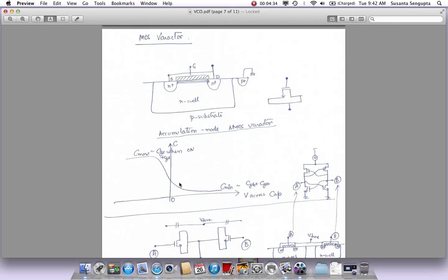So in this plot, to be consistent with this plot, what you have to say is the gate is fixed and the drain is moving. The gate voltage is kept fixed and the drain voltage is negative compared to the gate. Then this is heavily turned on and we're going to get Cmax. But if you kept the gate the same voltage, and you moved the drain to be more and more positive, so the source and drain value became more and more positive, then your VGD, gate to drain or gate to source, became negative. That means now you have depleted this channel of electrons and you have generated more and more holes, and your capacitance has gone down to CGDO and CGSO. So this capacitance movement will happen something like this. This is called the CV plot. What is the capacitance seen between these two nodes when, for this plot, the gate is fixed and the drain is being swept from a negative value to a positive value.